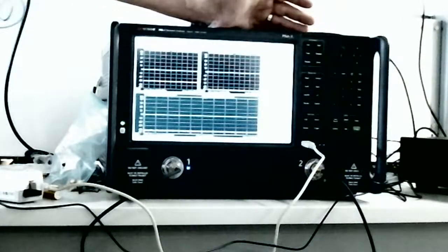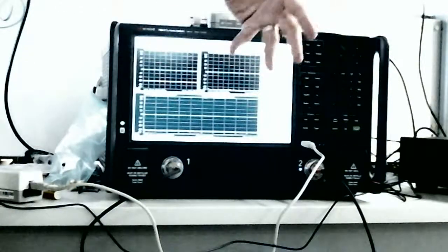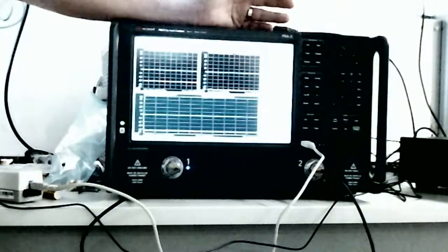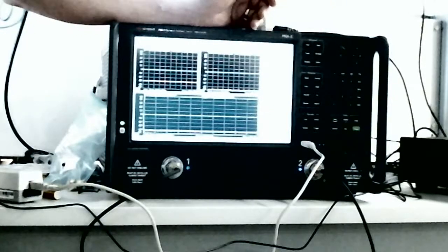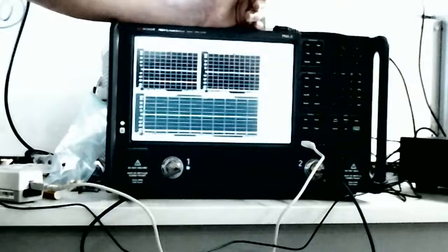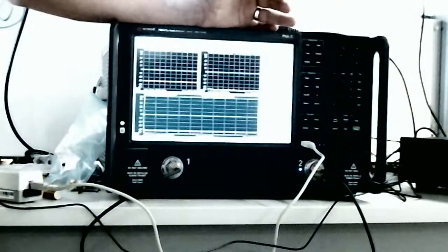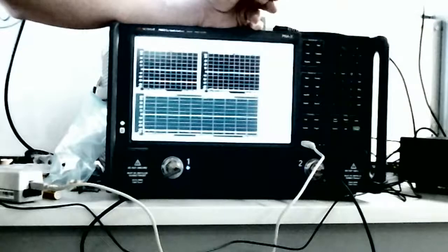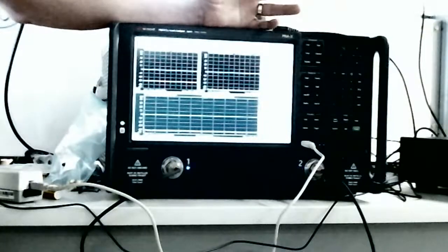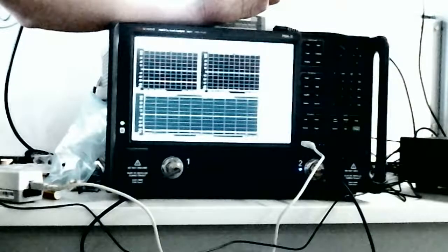No? Then all you're going to be doing is maybe putting some shielding around your antenna. Yeah, we have a microwave shielding box actually. So you have a shielding box, so put your antenna in, we'll do an S11 measurement. That's about it. Antennas are really easy to measure. Like I said, the only time it gets difficult is when you're trying to do quasi-optic experiments or far field measurements, and you have to do calibration.